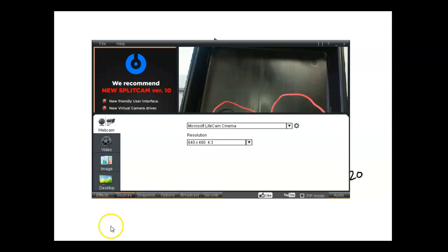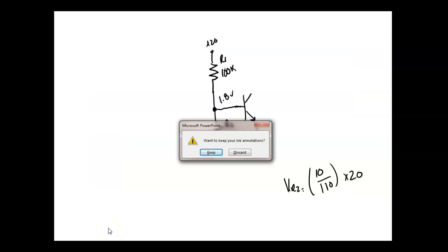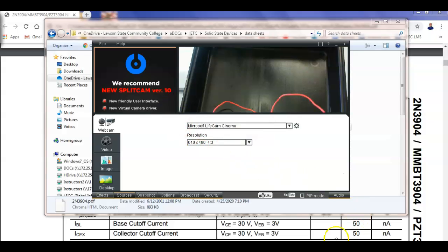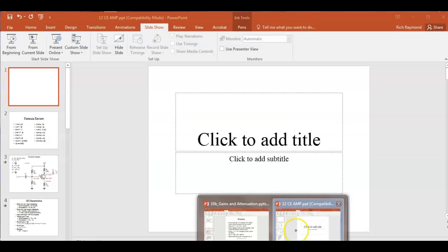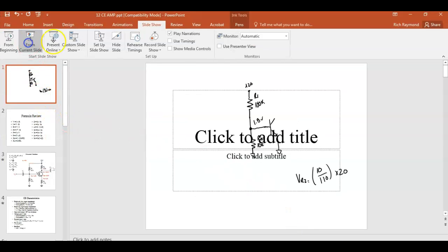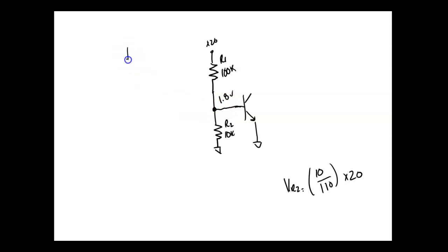So this is the circuit I have up here. This is a 1K. This is a 1K. Then I'm putting plus 5 volts over there. And I'm going to measure right here. So what voltage should that measure?